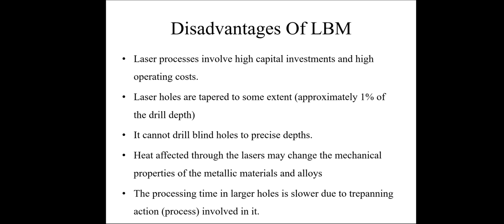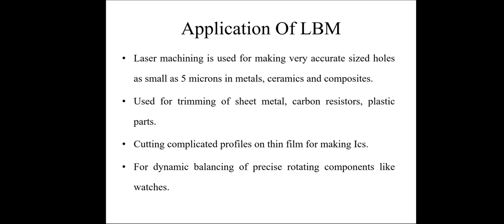LBM process. Laser processes involve high capital investment and high operation cost. Laser holes are tapered to some extent, approximately 1% of the drill depth. It can't drill blind holes to precise depth. Heat affected zones from the lasers may change the mechanical properties of metallic materials and alloys. The processing time for larger holes is slower due to the trepanning action involved in it. Next, we'll discuss the applications of laser beam machining.